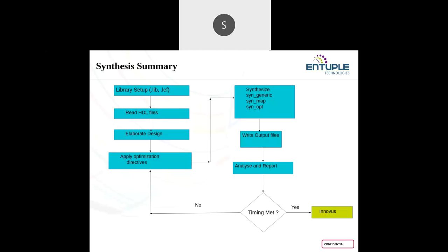Even if I have a high slack, it is not a problem, but it needs to be positive. If it is negative, only then will the tool say that path is violated. So whatever path is violating, the tool will try to add some cells into that particular path and fix the timing issues. Delay will be included and it will again optimize your timing issues. That's where incremental optimization comes into the picture.